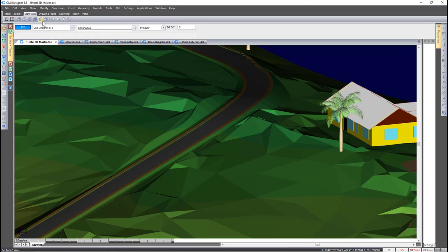You can go and define your own drawing plane. So in this case, you could go and select a drawing entity. I'm then going to select 3 points indicating the drawing plane. And this would just be CAD jump points.